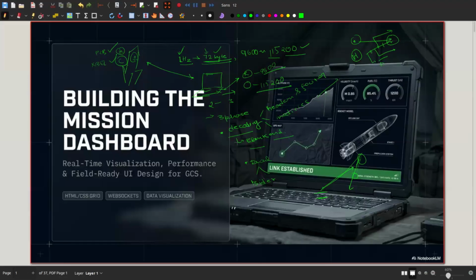Let's say the first value will be altitude. Altitude will catch bytes like 0, 1. So these are the bytes of altitude. The temperature will catch bytes like BC. So these are the bytes received for the temperature. And the third phase is basically you convert the bytes into float. In most cases, you use float.